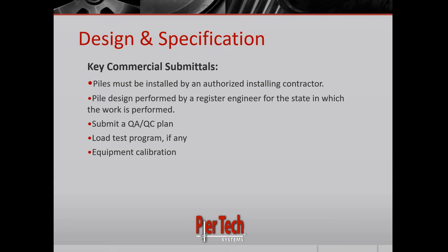So the best method is that IntelliTorque real torque monitor I talked about for meeting the submittal requirement. So if you have that monitor, it comes with the calibration, you can submit that and you'll be good to go. If you have the pressure gauge system, you may want to consider getting one of the real torque IntelliTorque monitors to satisfy this requirement.